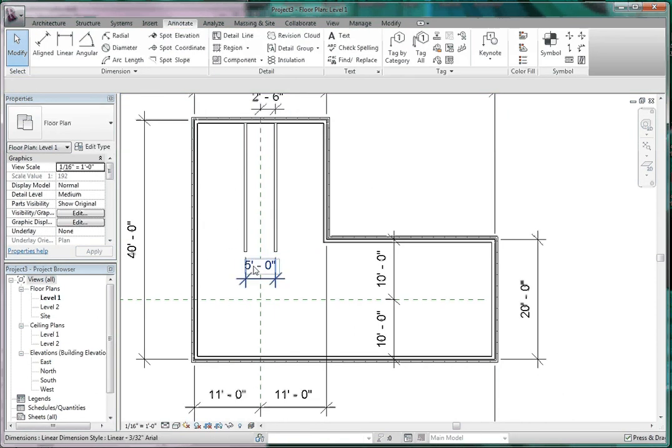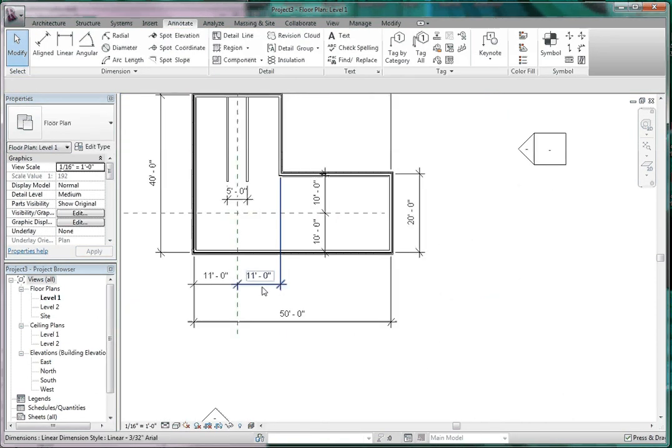So that's kind of what you want to do with your dimensions. You want to make sure your dimensions constrain your model, but don't necessarily constrain it completely, like in a horizontal or vertical direction, northeast, southwest direction. You still have the ability to rotate it around, but if your model is going to have specific dimensions associated with it, you want to make sure those dimensions are locked on the model so that items within the model, like the walls within the model, don't move anymore. Then this is a pretty good technique to do that.